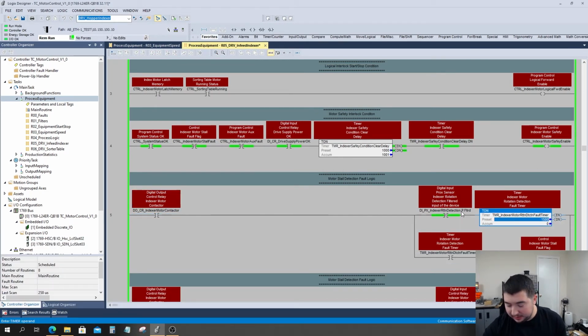Also, while we're here, I will increase that timer delay to 2 seconds, because as we were seeing earlier in the video, that rotary disk wasn't spinning quite fast enough and was just about to be an issue for the fault reset, or for that timer delay.